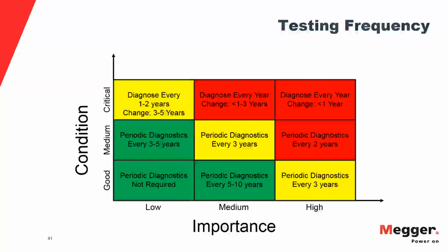Something like a switching power supply in a computer might have enough high frequency components in there to affect you. Some high frequency, some hundreds of megahertz type of signals that are inducing these signals into your test equipment.